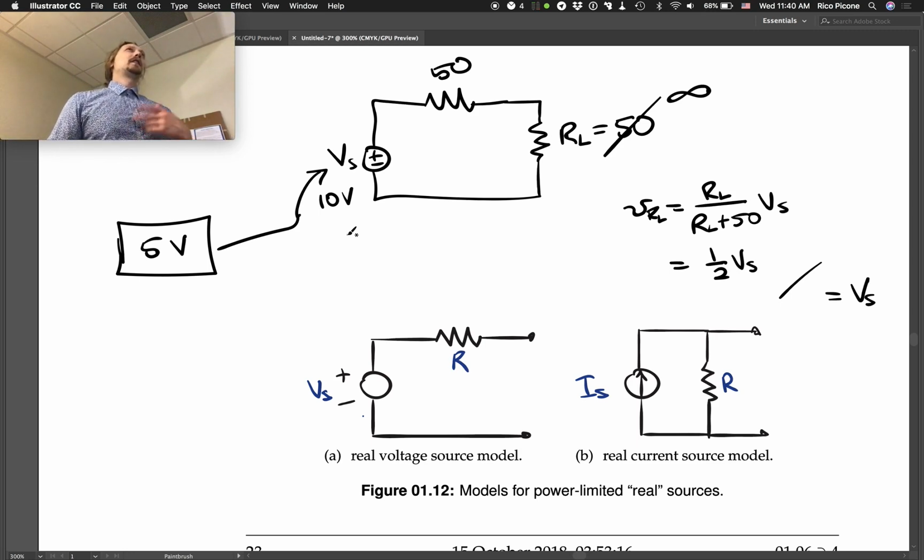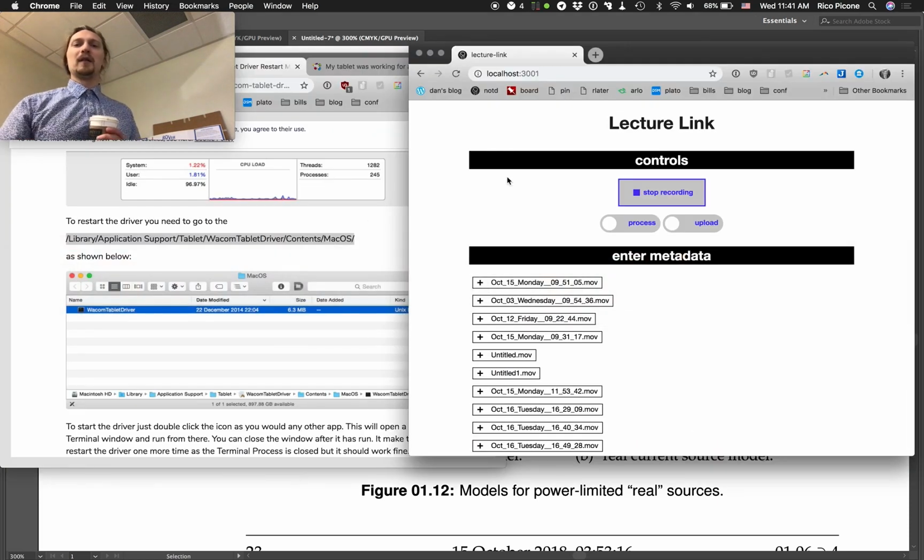And I have mixed feelings about these modes because they generally just cause confusion, and they don't really have a lot of benefit other than that. So be cautious of that. I've seen them get into that mode by accident. Actually, when I went in there, I was trying to measure some voltage, and it came out to be like 150 volts, and I was like, whoa, that can't be right. And I went in and I found that it was in a 10x mode, and then I was like, okay, that makes sense. Okay, I'm gonna stop rambling now and let you guys